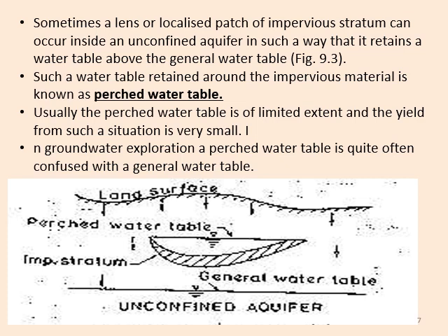If we install or penetrate a well in this zone, we will get this impervious strata and consider it the strong foundation, so we will penetrate the well up to this level. But here water is of limited quantity, so when we pump out, we will get a limited quantity of water.